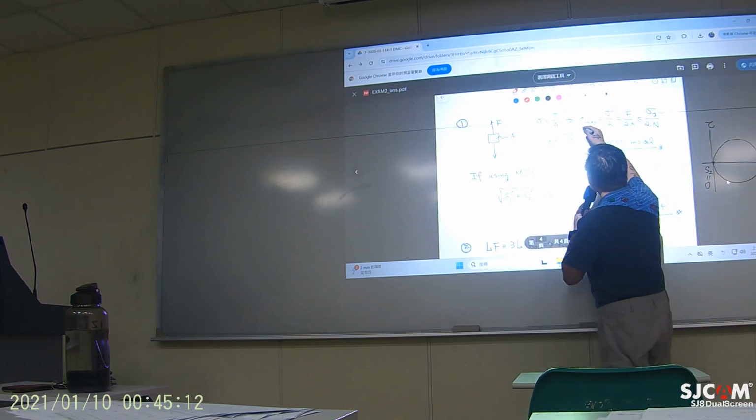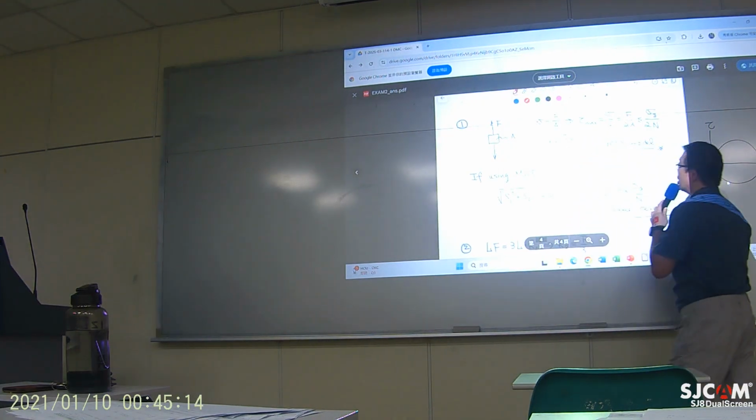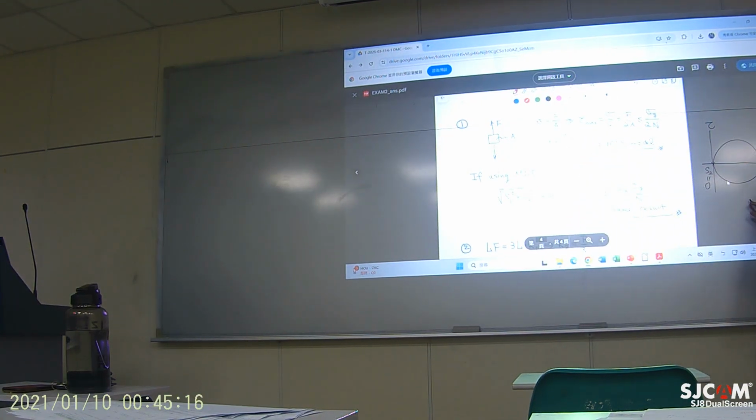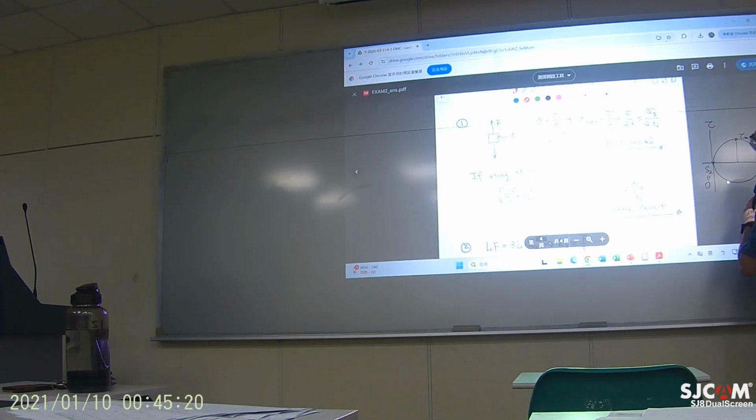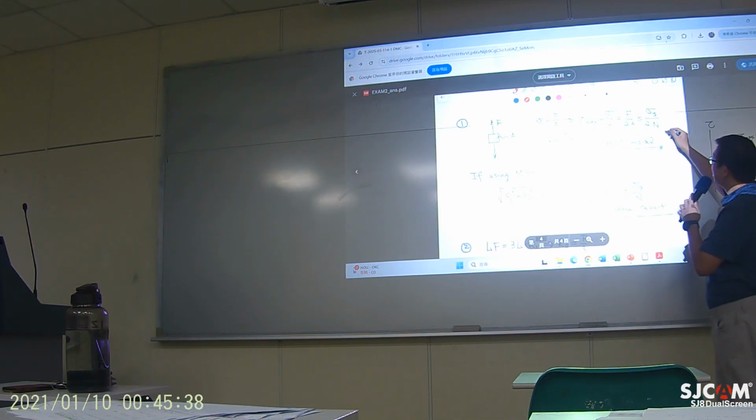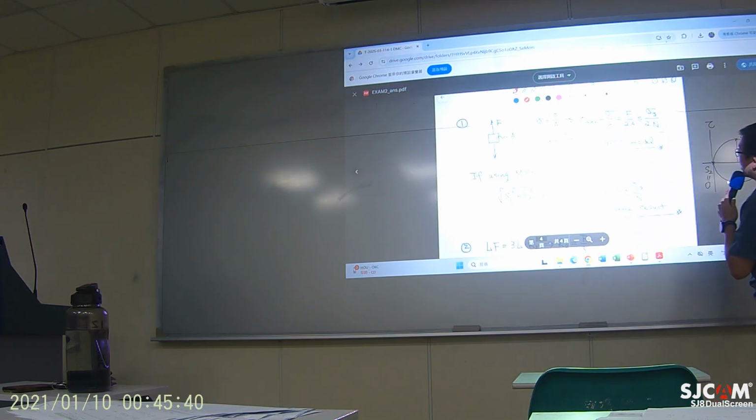So this is by maximum shear stress model. In Mohr circle, the maximum shear basically is 1/2 of the sigma, okay? And this has to be smaller than the yield strength divided by 2 over safety factor. Okay, so that's why it's like this right there.